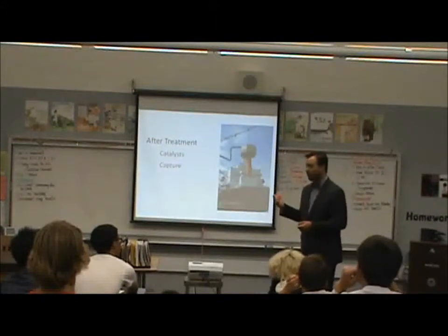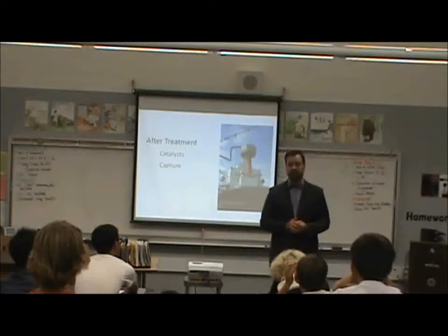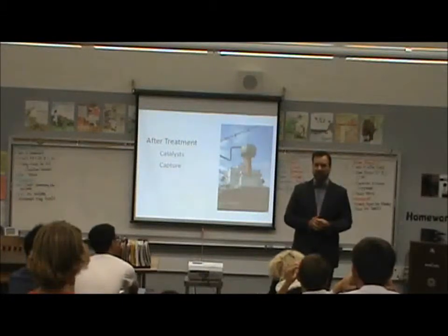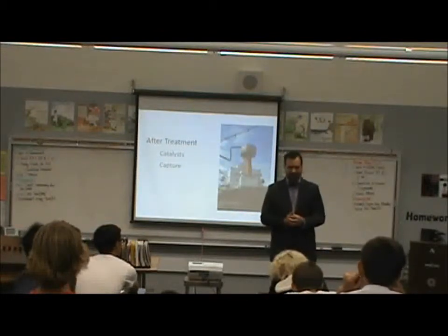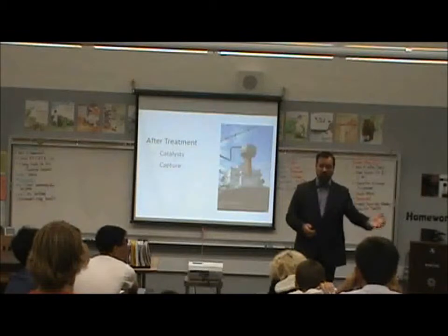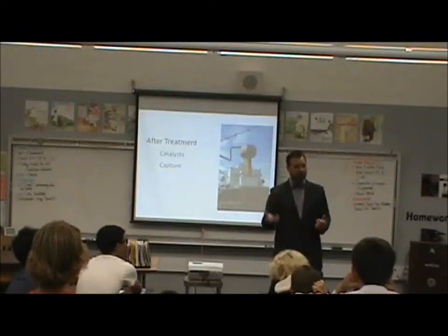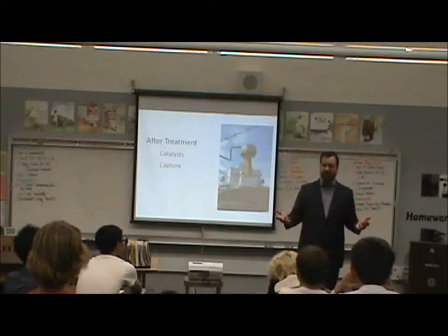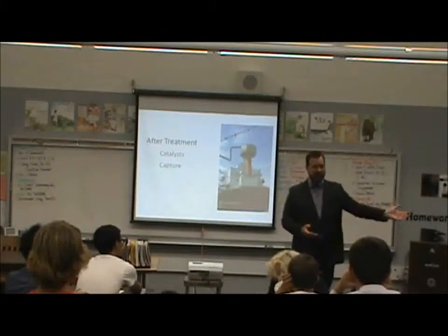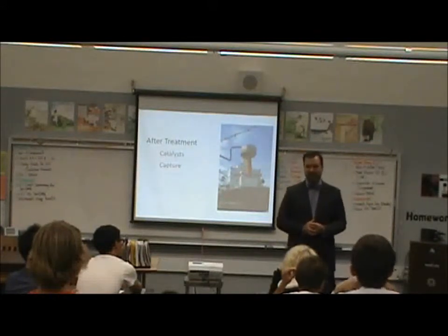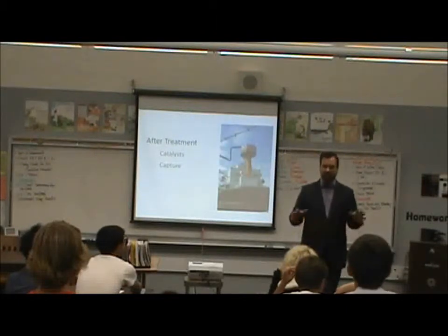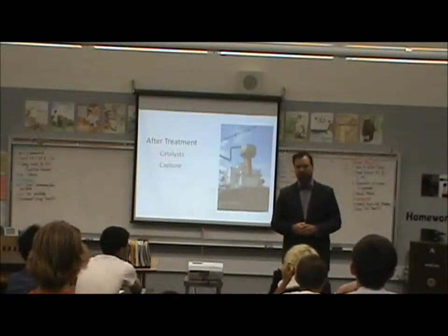The big thing that we did in the ports is that technology was finally applied to diesel trucks, which is an incredibly challenging thing to do because the chemistry is different. One of the things you'll probably learn if you don't already know about catalysts is that one of the things that helps drive a catalytic reaction is heat. When you have high temperatures and the right catalyst, you can make reactions go quickly. That's what your catalytic converter does in the car. It eliminates the pollution that your car produces by passing it over a catalyst at high heat. Diesel does the same thing. It's much harder in diesel because diesels burn much colder, with much less heat than gasoline cars.